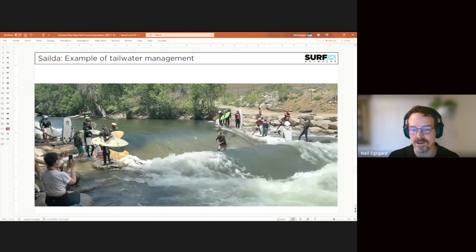This directed more water into the wave channel, which provides more energy for the wave, and it pushes back the tailwater. You're balancing out the energy of the water coming down with the force of the tailwater pushing back on it. So by forcing more water through the channel, they increased the drop from headwater to tailwater, and that helped push the wave back.